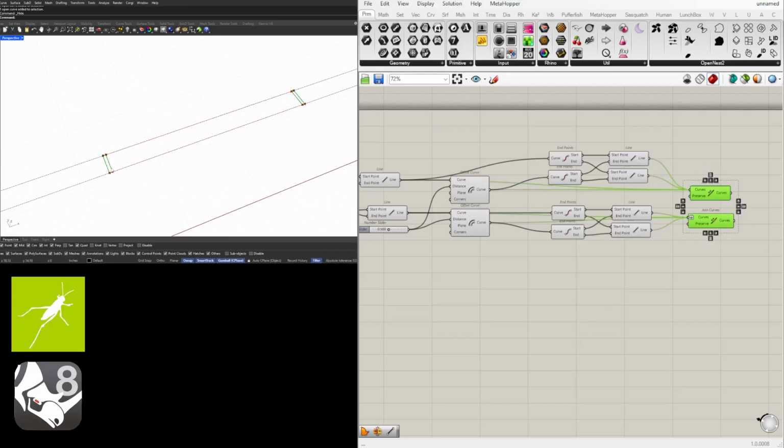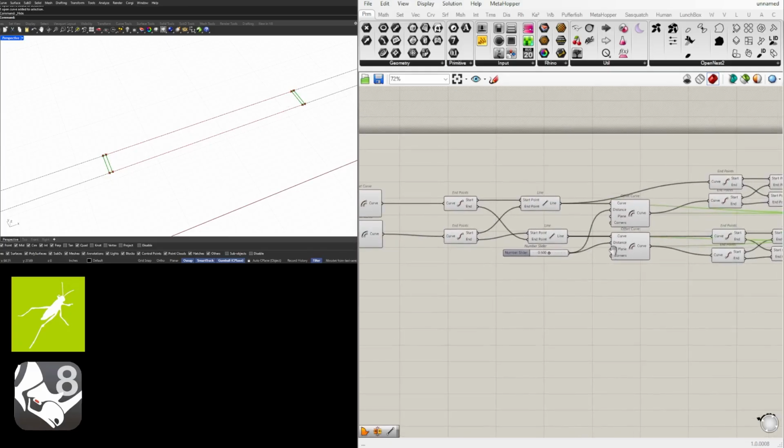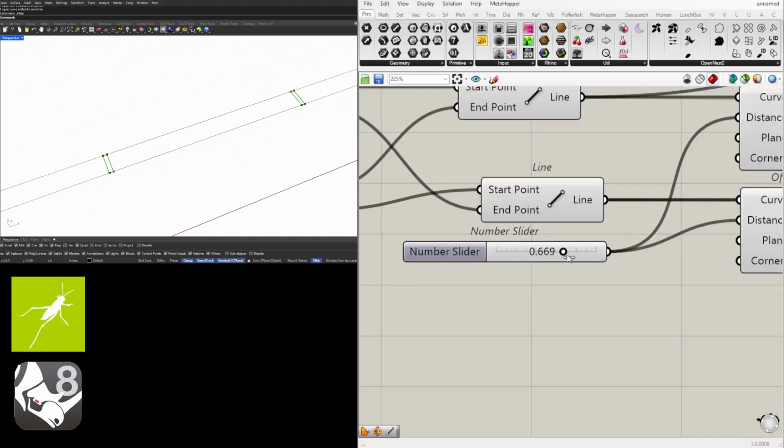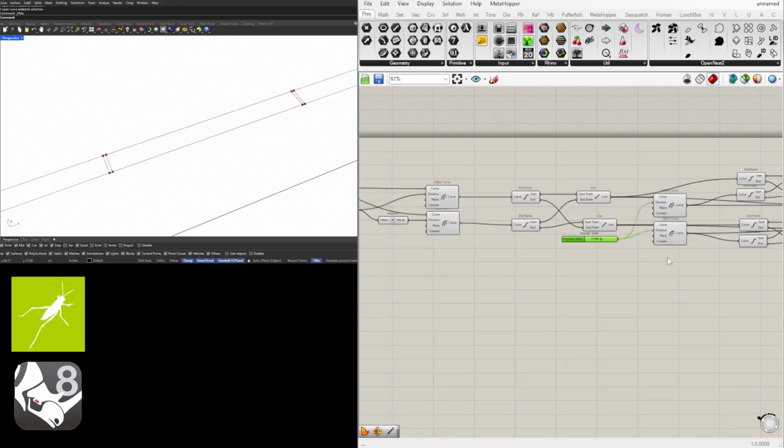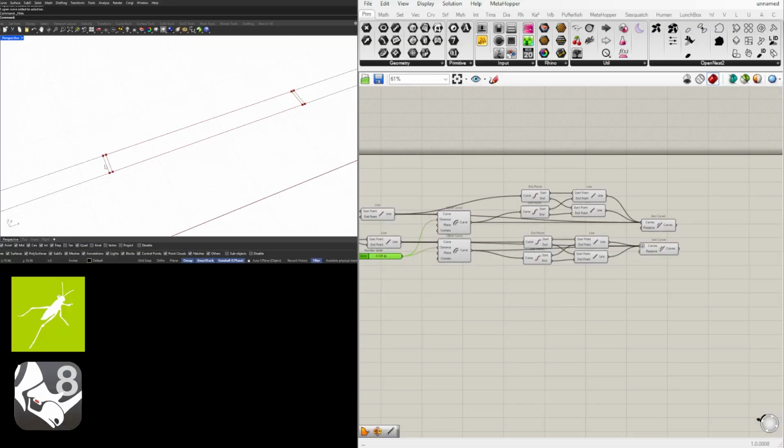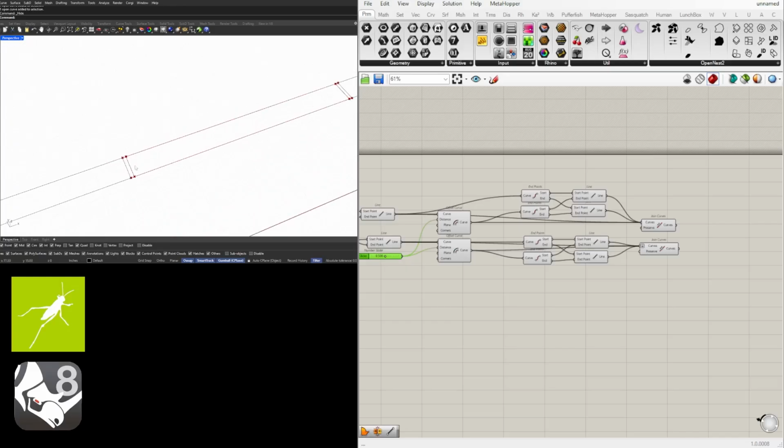So far we've created the door frame, and we can change the size of that here if we want to. That's also going to depend on your manufacturer. Typically, you would actually bring this out here, and that would create the rough opening. But since we're just using this to draft, this is just going to give us a little bit more detail. So when we create the door, all of this information will be brought into the design.